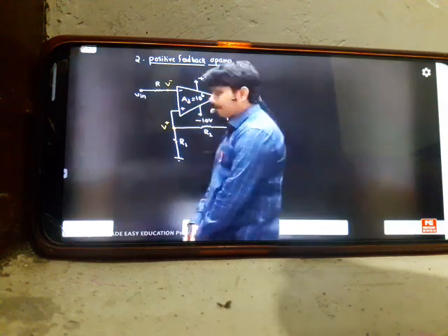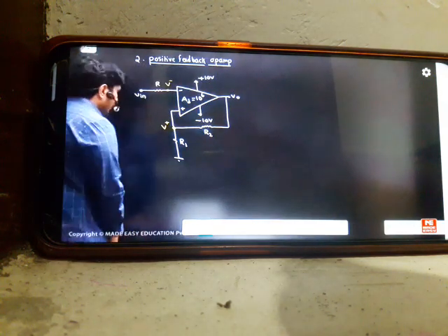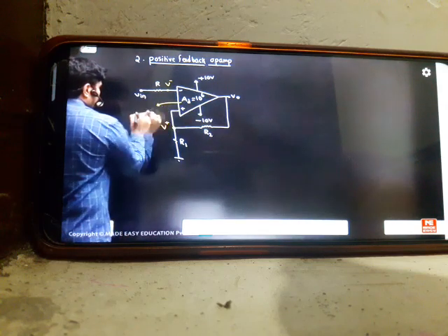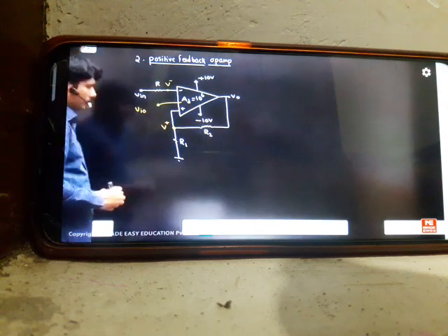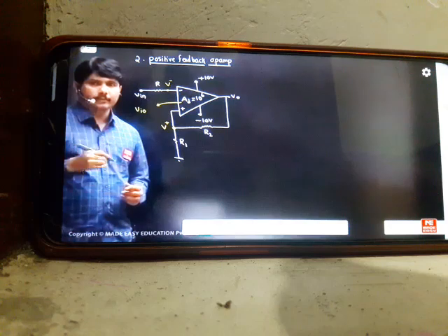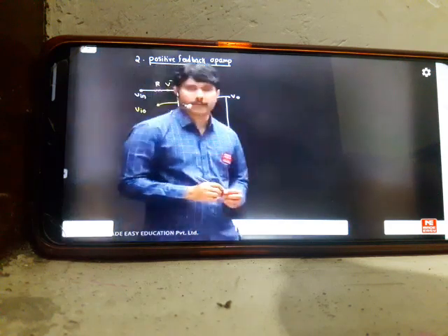One thing when you start the positive feedback analysis: one important point is that already inside the op amp we have some offset. Vio offset will be there. So in positive feedback systems or open loop systems, we don't want to nullify these offsets. Offset is something we want to nullify only in negative feedbacks.